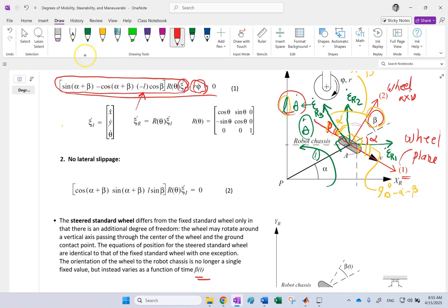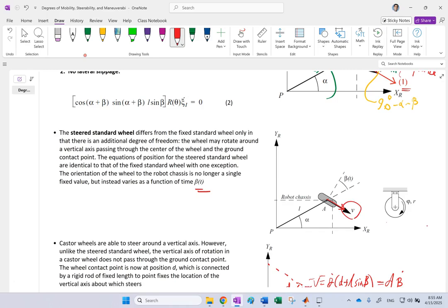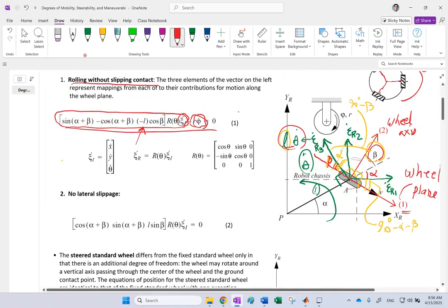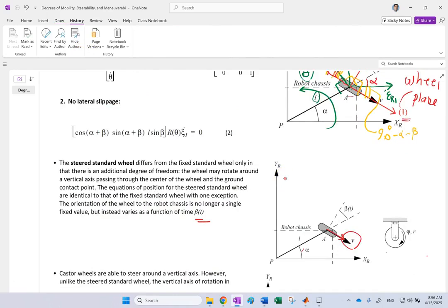Okay? So the wheel of the robot can move along this axis 1 with velocity v, and all I'm saying is that these L, alpha, beta, and everything should be related to each other as well as phi dot. I'm not really taking away the motion along the direction of the wheel. You see, I'm not limiting that. But when I say you cannot move in this direction at all, that v equals 0, I'm limiting that lateral motion.